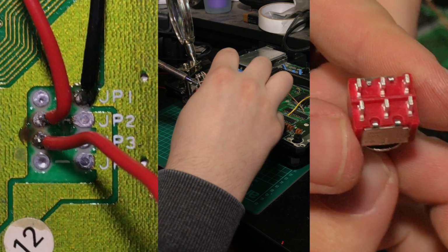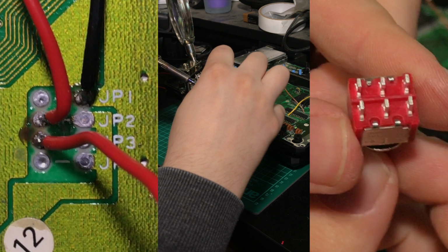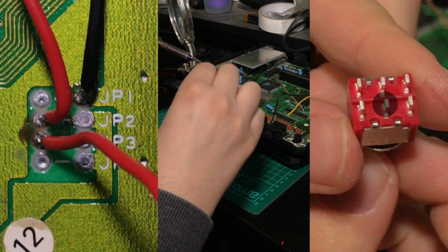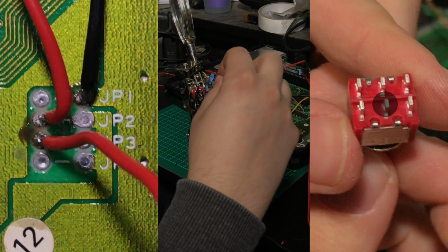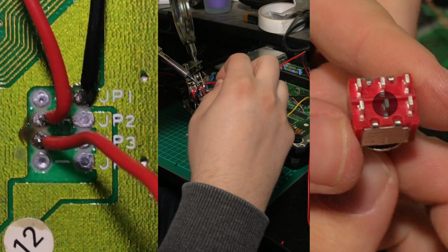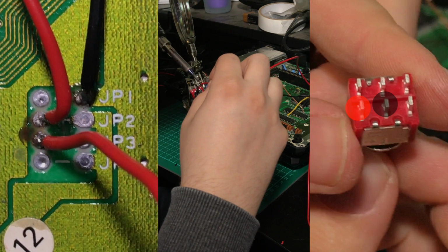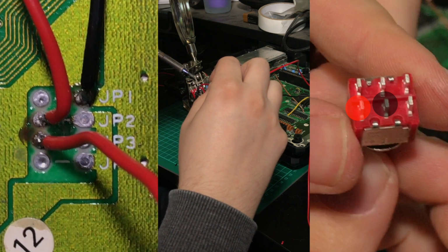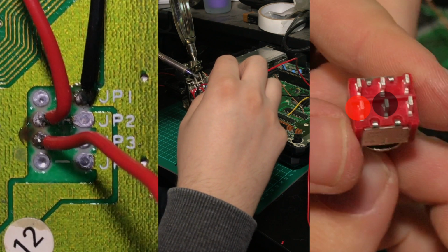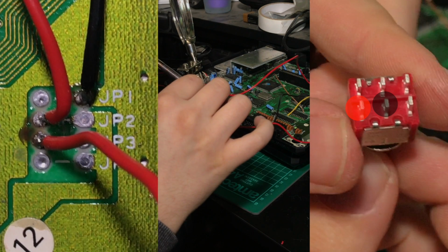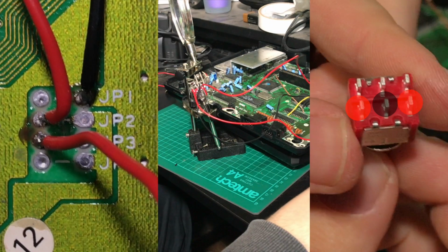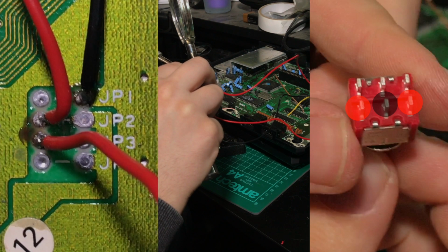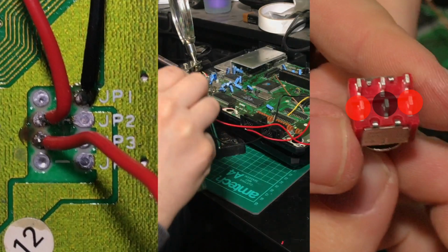Now you need to solder the wire leading from the right hand JP1 or JP3 pad to the center contact of your switch, which will be our default American region option. Next, take the wire from the left hand JP2 pad and solder that to one of the left or right on positions of your switch. Which one doesn't matter, it's just your preference, but this will be your Japanese region 60Hz option. Finally, you can solder the wire of the left hand JP3 pad to the other on position of your switch, and this will be your European region 50Hz option.